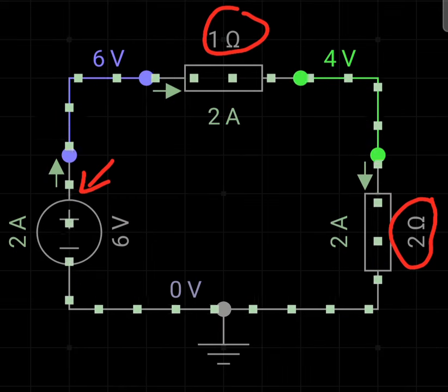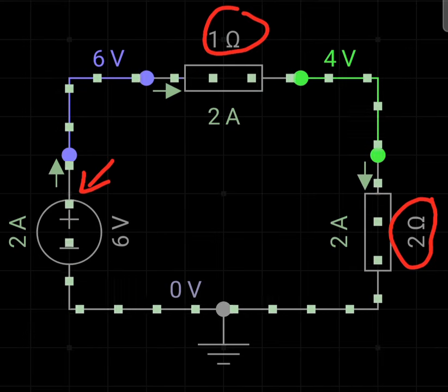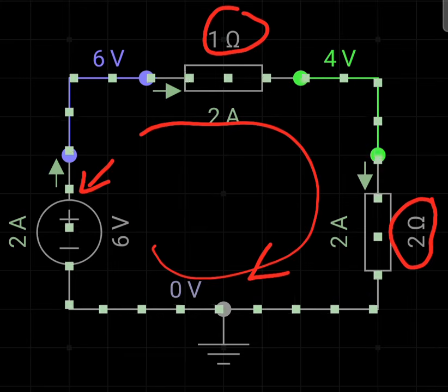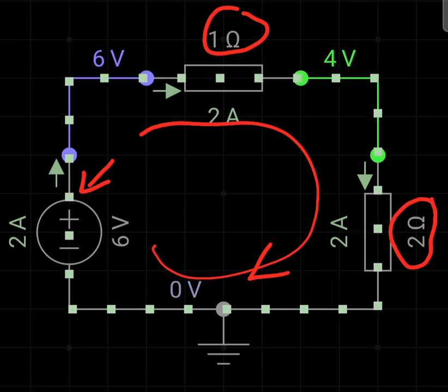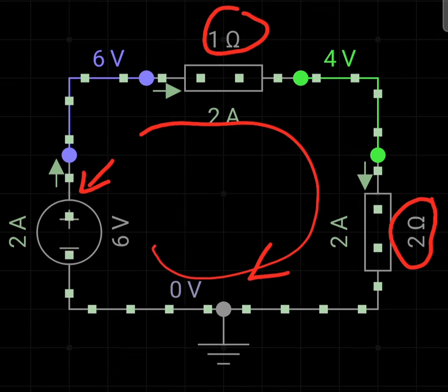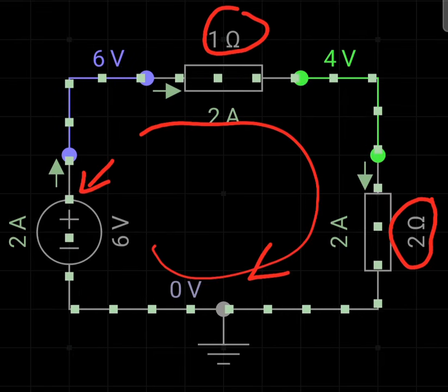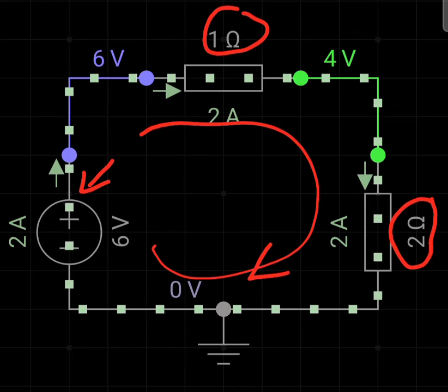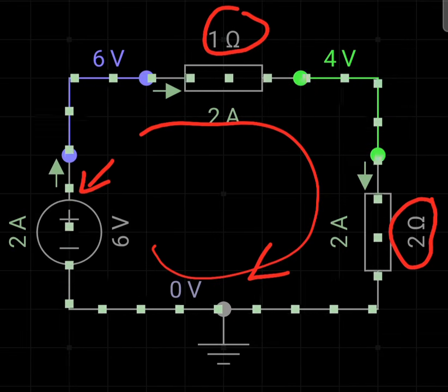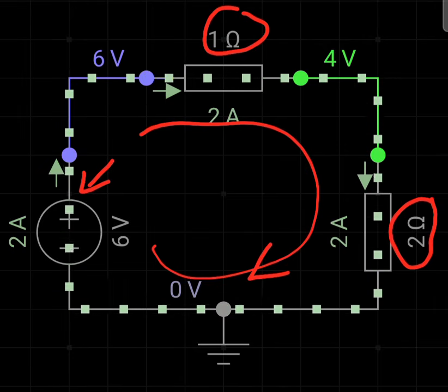And because the circuit is completed, or there is a closed loop, as you can see, the current starts flowing into the loop, as also shown by the animation. Now the question is, what is the value of that current? As I said, we have got a 6 volt DC voltage source. There are two resistances connected in series, 1 ohm and 2 ohms.